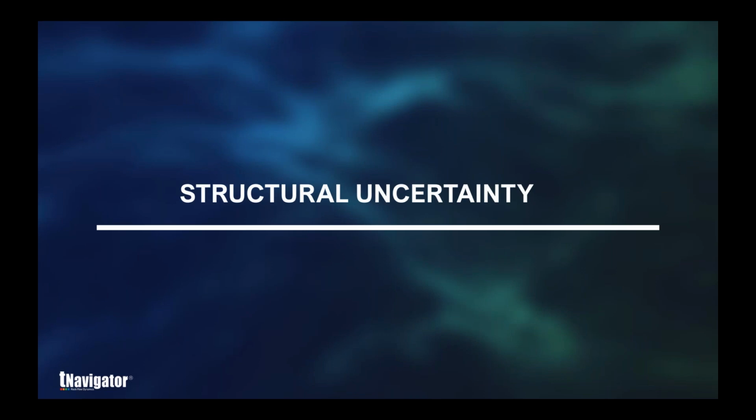Looking at our structural uncertainty as well. We've managed to capture our first uncertainty with our facies model, looking at how we can create multivariants, with these local variables tables that allow variables to be referenced and output new iterations for each case that we can view in 3D. We can also look at structural uncertainty here. Within Geology Designer, we can assign uncertainty based on our horizons and also our faults, and we can do this a number of different ways.